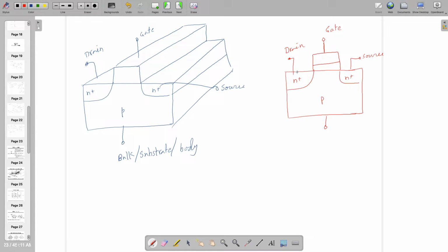Right? But this is what I told, the interchangeable characteristic. It's valid only for a few amplifier schemes. There is one scheme which is known as common drain amplifier. It's not valid there, so we'll study that. But till then, assume that source potential will be lower than drain. And if you are looking at the top view, it will look like this one. But I'll explain this a little bit. This side is drain, this side is source, and this is gate, right? That is how it looks.